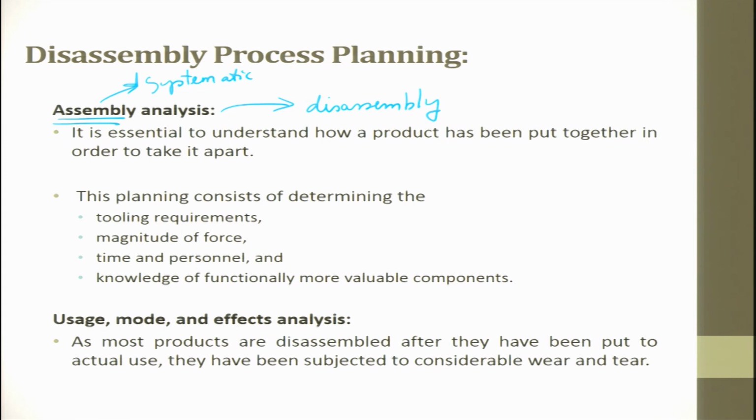In fact, when I was traveling abroad, I was completely fascinated by the way people dismantle a complete product and then assemble it back. They have a procedure. If there are 20 screws, they say, okay, this screw has to be done first. They have given even numbering for it. So, systematically they remove all the parts, then do whatever maintenance is needed, and then they follow the reverse of it in a systematic manner to assemble.